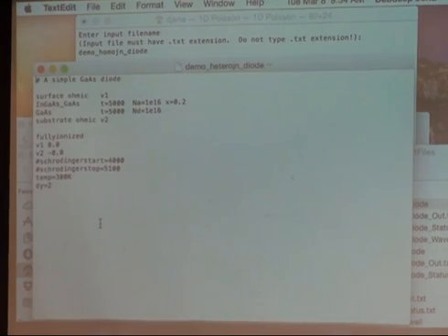So what we have done here is just a plain heterojunction diode, pretty much exactly like what we did here. So we have a gallium arsenide N-type, but we have indium gallium arsenide P-type with 20% indium. So it's a narrower band gap material, and that's P-type on the top. So I have still turned off Schrodinger, but I'll now turn it on and see what happens. Okay, so we run that.